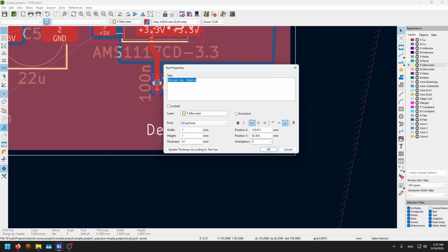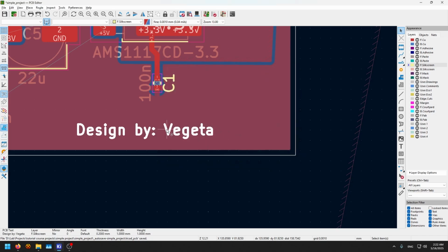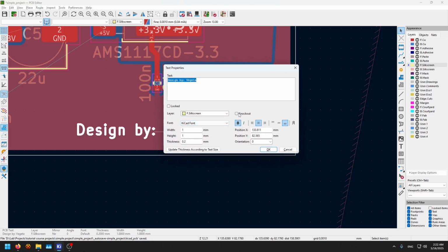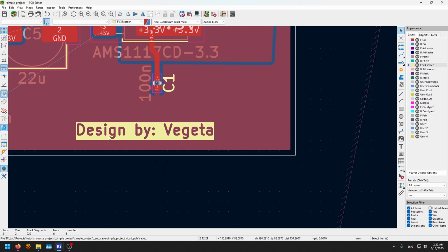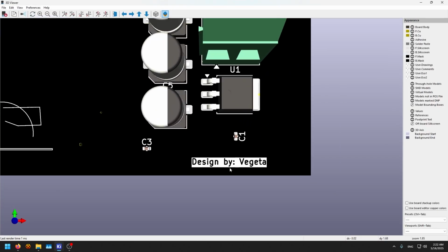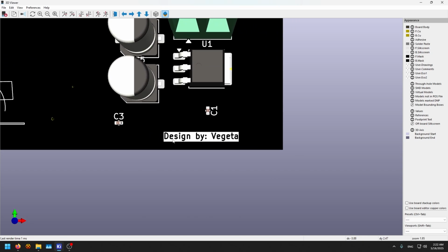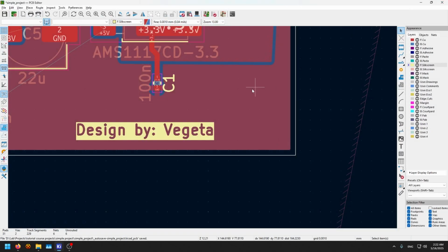The font, the everything, the alignment, the bold, for example, and there is a feature called knockout, which is something like this. See, now the words themselves are not solder mask, but everything else around them is, something more of an aesthetic kind of thing. Drawing tables, drawing boxes, whatever. Draw orthogonal dimensions if you really want some dimensions like this, but it's not AutoCAD, so don't do that.